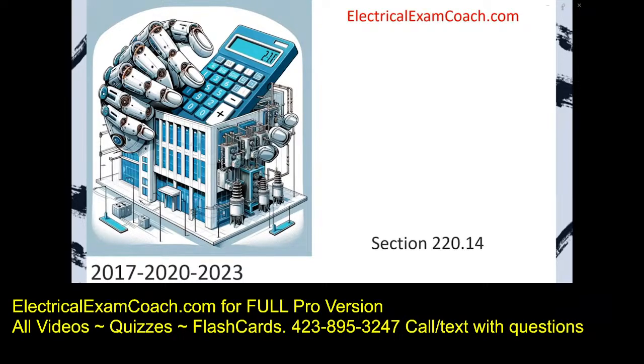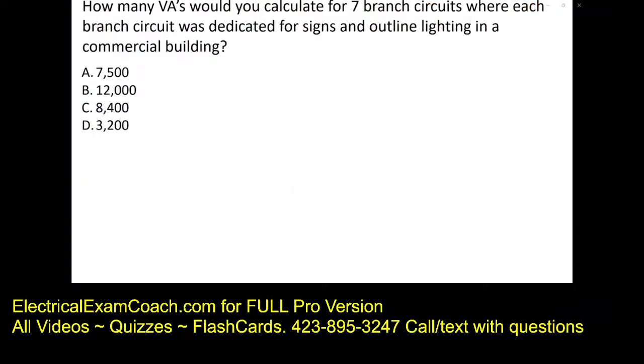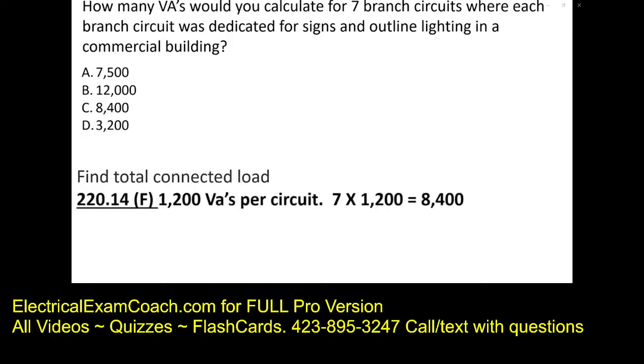Let's get to it. How many VAs would you calculate for 7 branch circuits where each branch circuit was dedicated for signs and outline lighting in a commercial building? Step 1, find our total connected load. For this, we're going to go to 220.14(F), and it lets us know that for each circuit, it's going to be 1,200 VAs per circuit. We have 7 circuits multiplied by 1,200 equals 8,400 VAs.